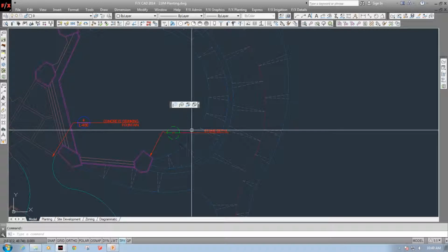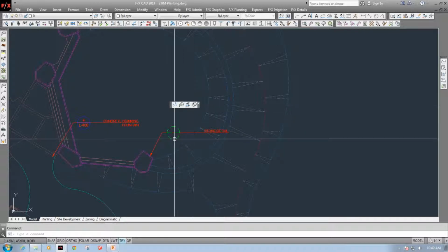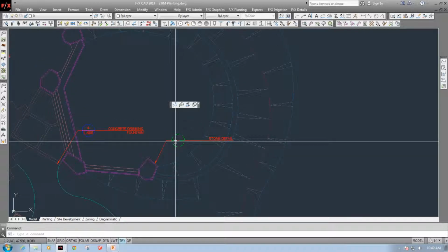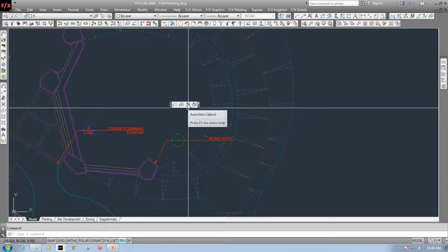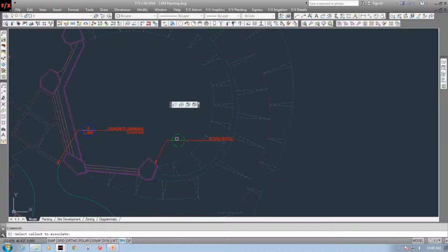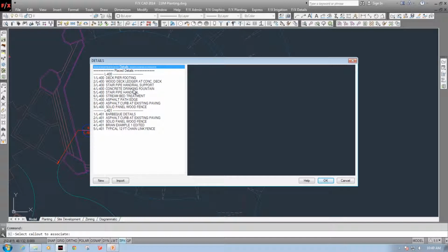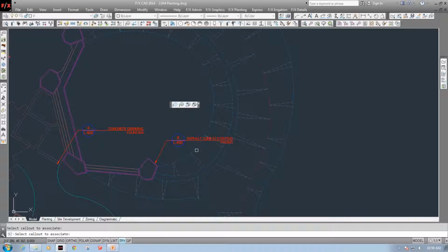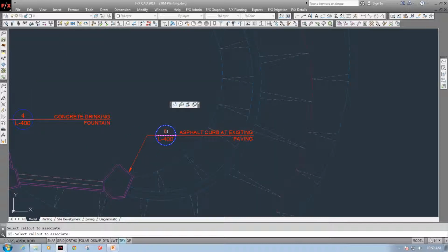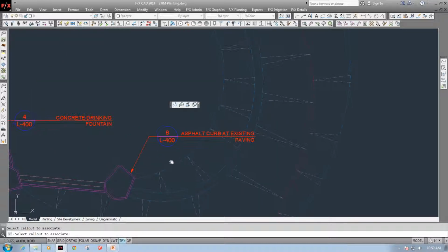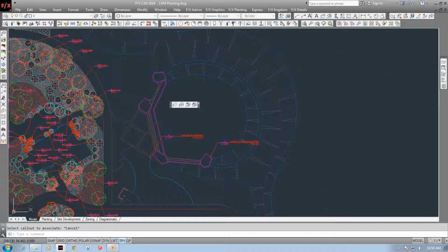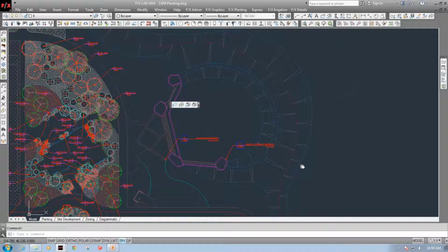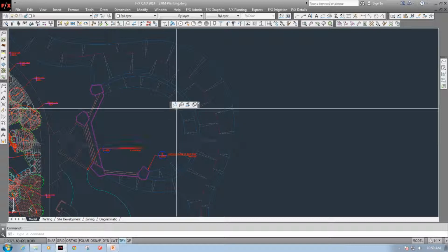Now to go back to this one, I remember I did put that detail in my plans, and I'm ready to associate it. So I'll click the Associate Callout button, and I'll click the callout, and I'm going to say this is going to be my curb, and say OK. And then automatically, just like that, the title is updated, the detail location and callout is updated and ready to go. So now it has automatically gone through and associated my callouts.